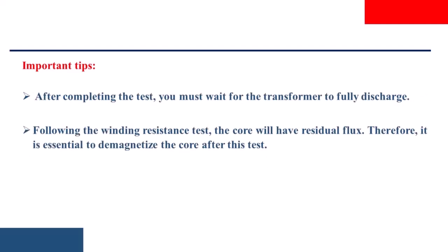After completing the test, you must wait for the transformer to fully discharge. Following the winding resistance test, the core will have residual flux. Therefore, it is essential to demagnetize the core after this test.